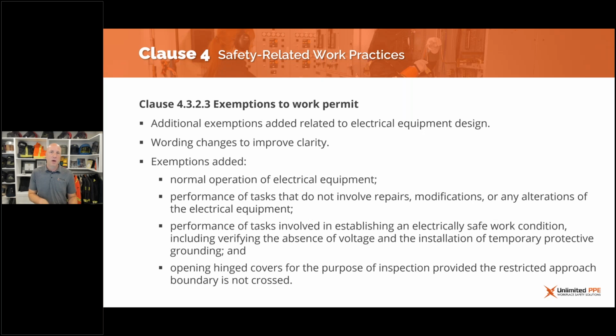They still are required to have all their pre-job briefing and planning documented. They still are required to have a shock and an arc flash risk assessment completed, but it's that last step of the energized electrical work permit that would be exempted for these examples.